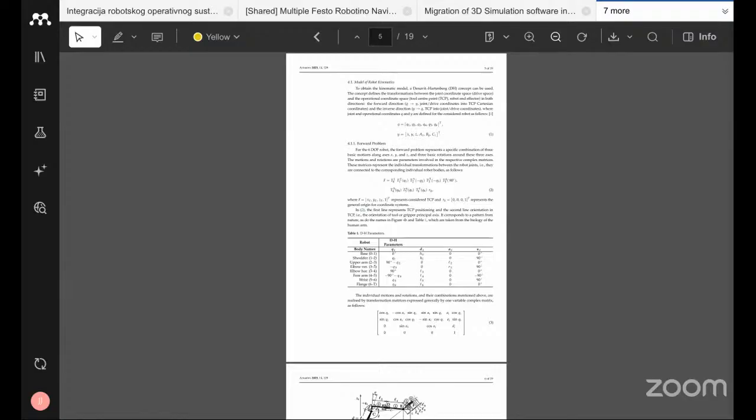The simple working is that the robot controller receives the joint values Q1 to Q6, and every joint produces this DH matrix. Then multiply these matrices from the base to the flange, or from the base to the gripper, so that the gripper or TCP gets this position.